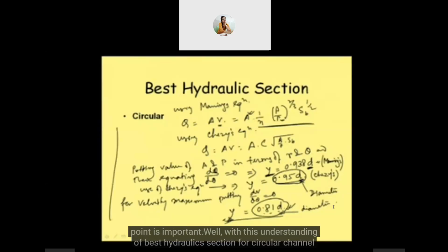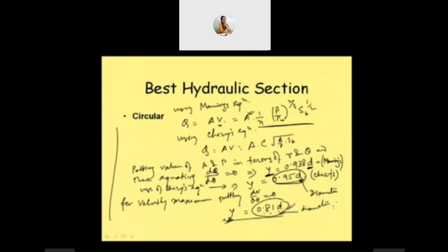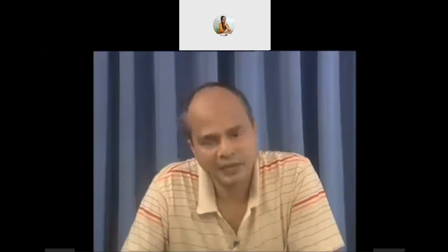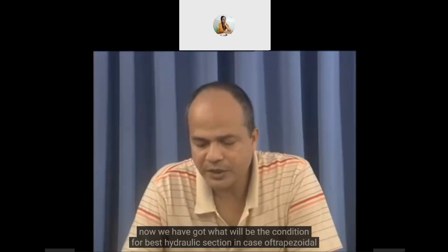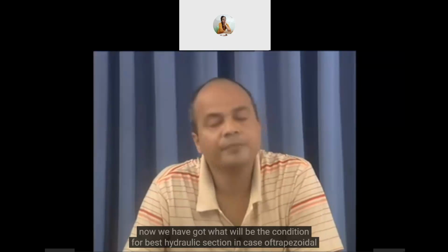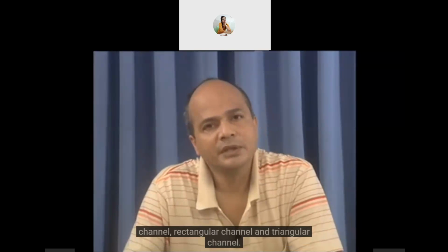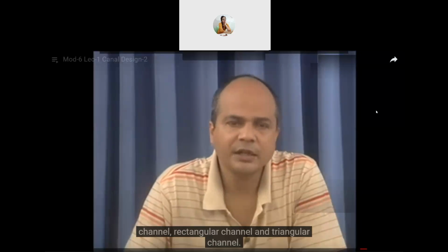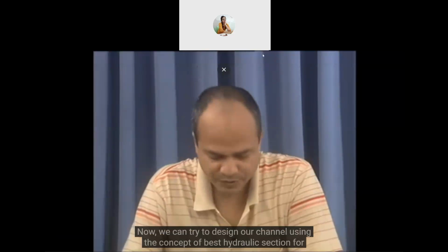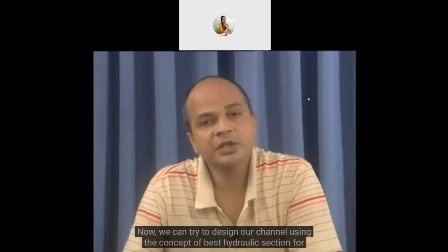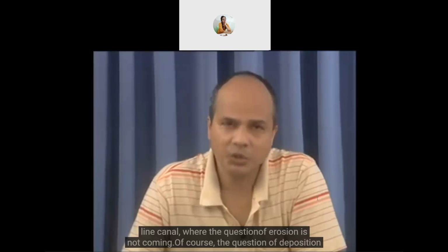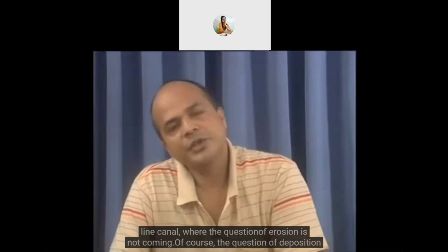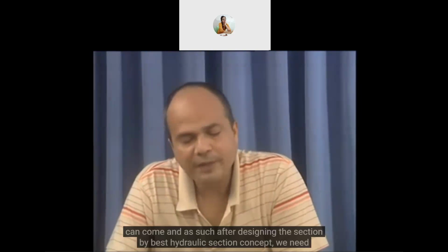Well, with this understanding of the best hydraulic section for a circular channel, now we have got the condition for the best hydraulic section in the case of trapezoidal channel, rectangular channel, and triangular channel. Now we can try to design our channel using the concept of best hydraulic section for a lined canal, where the question of erosion is not coming. Of course, the question of deposition can come, and as such,